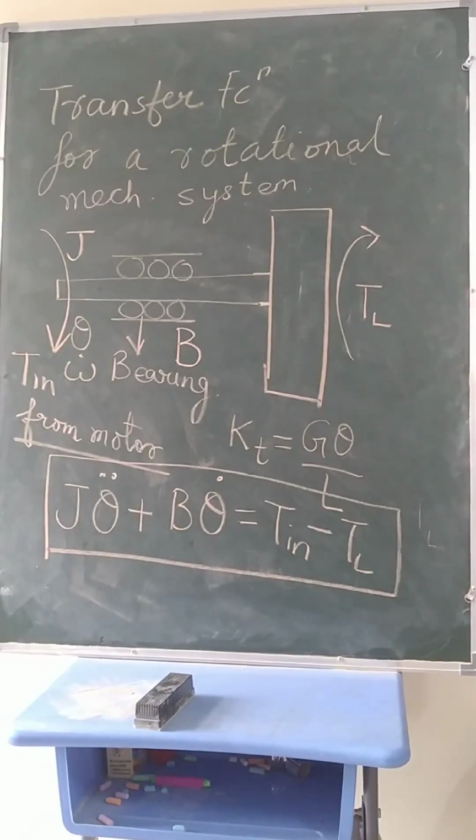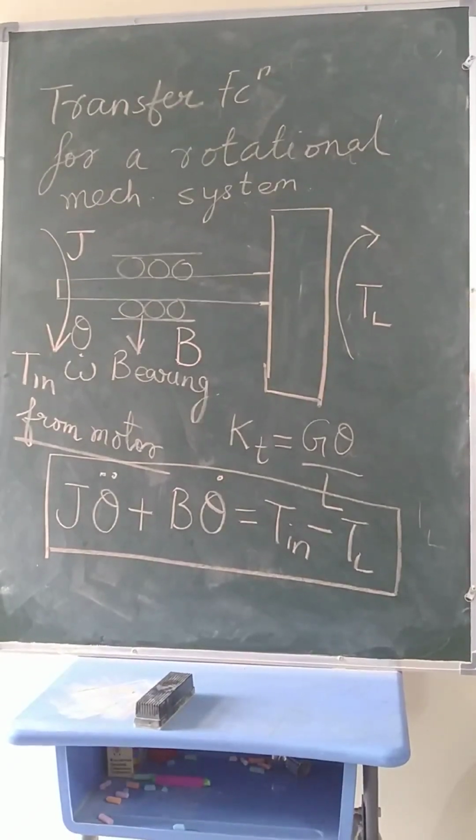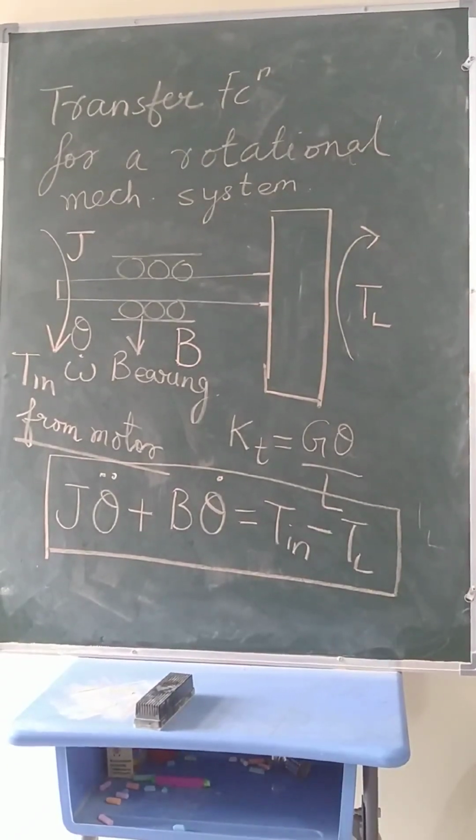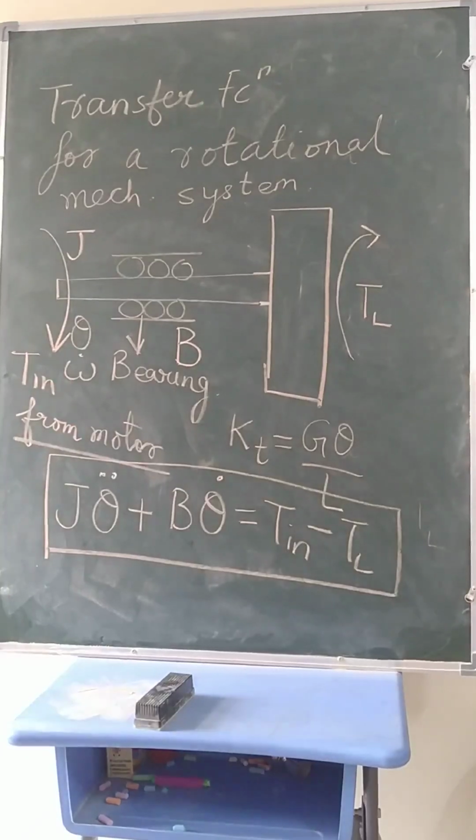Right? If the robot is used for picking and placing some object, even then we want it to be very precise. So you need to use feedback control in those cases. But feedback control will come later. First we need to model the transfer function of the system. Right? So your output can be theta if it's position control. Your output can be omega if it's speed control.